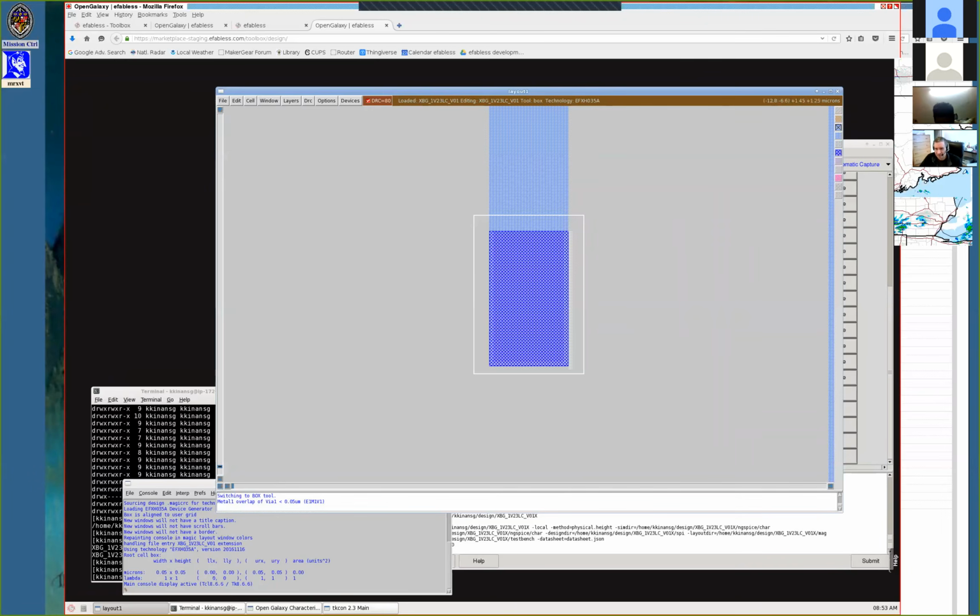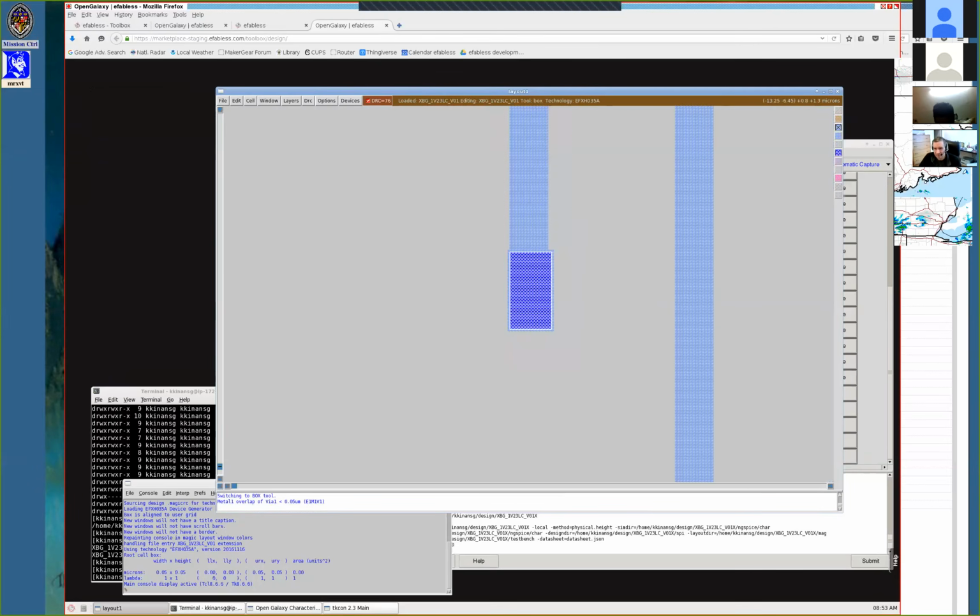Well, the easier way to do this is just to... I didn't mention that while you can create layers by clicking the middle mouse button on here to fill in the box, you can also delete everything in the box simply by clicking the middle mouse button on the background. So I'm clicking the middle mouse button here with my pointer on the background, and it's gone. So here inside the cursor box, I can go over to devices and via 1, and it draws me a via that has all the metal surround already done. So I think that's the best way to work with a wire.